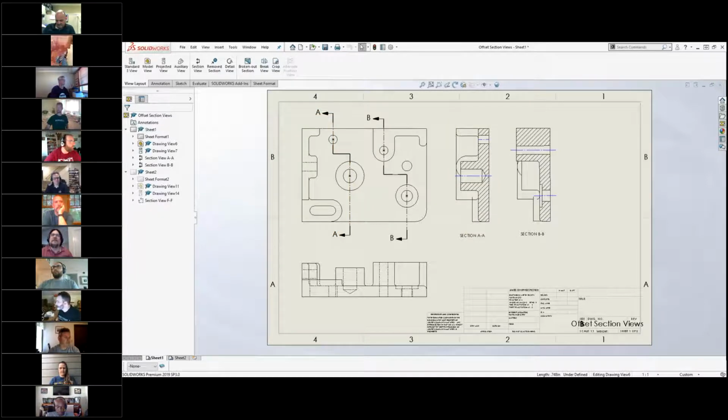All right. So Eric, while you're on section views, you mentioned the section view tool that you're versed in. I've always continued to do it this kind of legacy old school way because I get frustrated that the tool, oftentimes I see in other people's drawings and my own when I've tried it, doesn't always create a relationship to a feature that I'm trying to section through, and so things can tend to move on you.